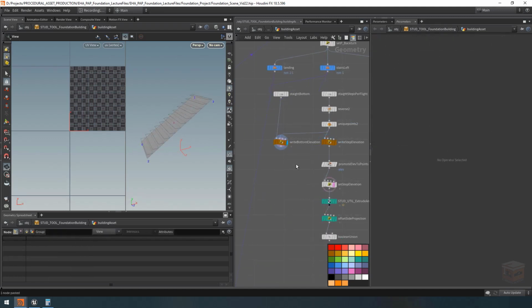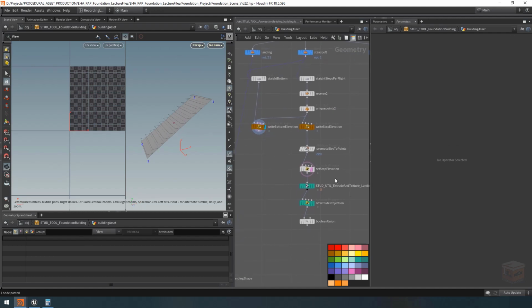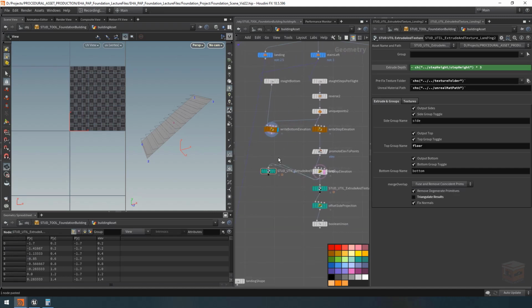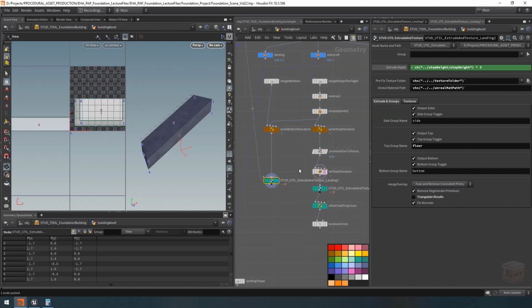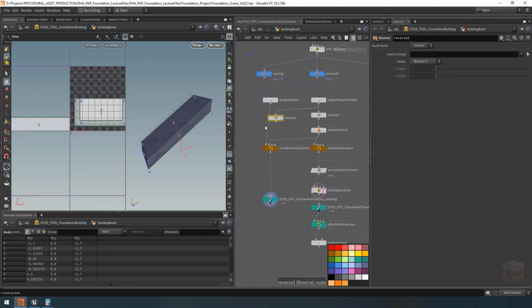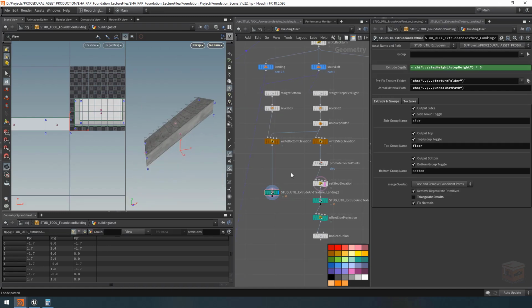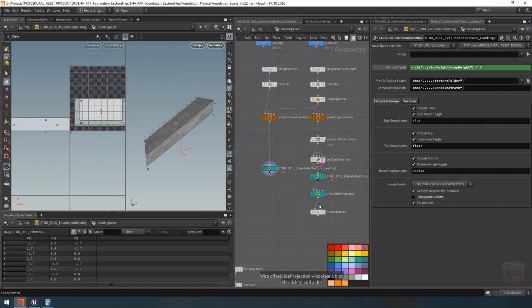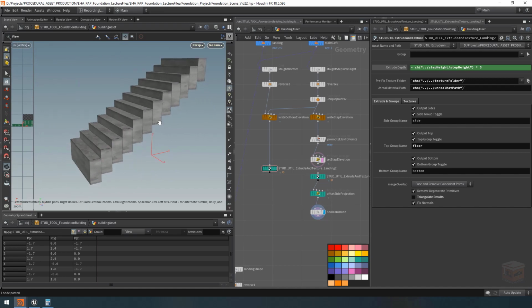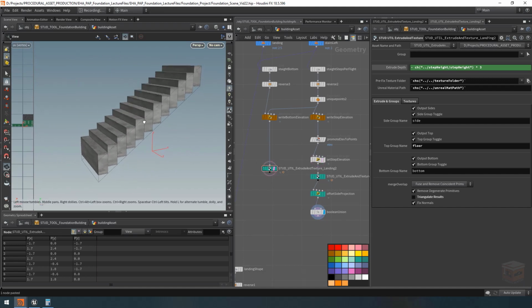Okay, so next, let's also give this thing some depth so we can start using it as a cutting shape. Let's grab our extrude and texture node over here, copy it, and let's plug it in. Now again, we are extruding down, so let's also add a reverse node up here. So we have a properly oriented shape. And then we can take this and we can start cutting our current shape. So this one with that.